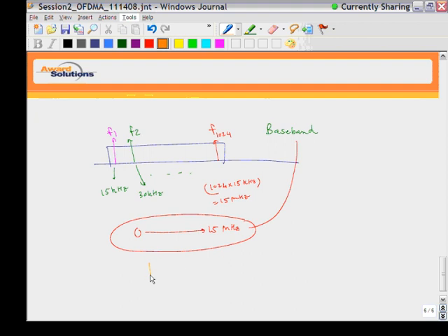After you do frequency up conversion, we will shift that spectrum all the way to RF. So then we will have the center RF. Let's say we deploy at 700 megahertz. That is one of the carrier frequencies at which LTE will be deployed. Verizon got a lot of spectrum, and AT&T has some spectrum at 700 megahertz.